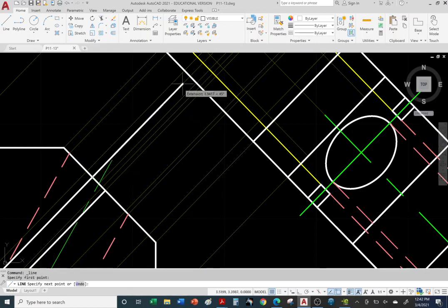We're going to follow the construction line, right? Follow the yellow brick lines, and yeah, you heard what I said. Follow the yellow brick lines, right? And there's the slot, that's the depth, and close it off. Okay, and right click enter. Okay, so there is the slot. Let's go ahead and use the grips to shorten it and hit escape. And there it is. Ta-da!